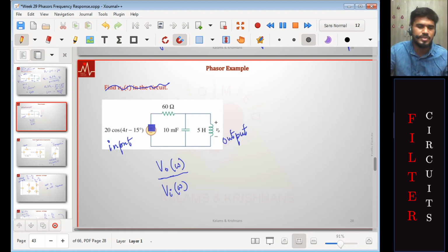So where do things like this appear? Quickly, you have a signal here, and there is a signal source here. Instead of this voltage source, you're measuring some body potential, some muscular activity or something like that. There is some processing in the electrical circuit going on, and you are reading the output here. You're removing noise. You want to enhance certain frequencies, based on whether it's EEG or ECG. You want to understand what happens to the ratio of these two amplitudes at different frequencies, not just at one frequency, right? So output over input.